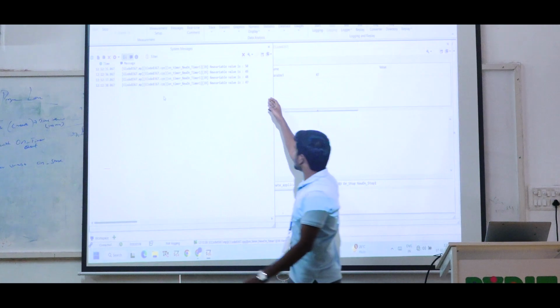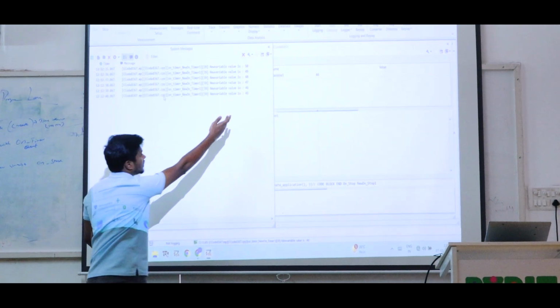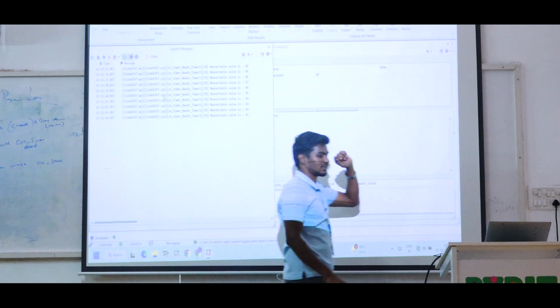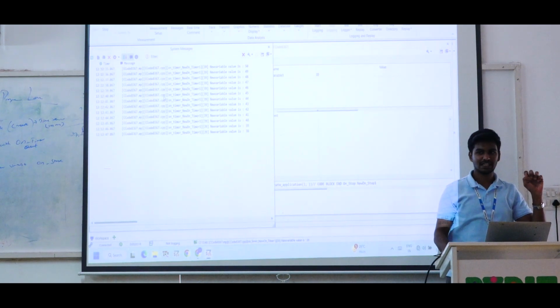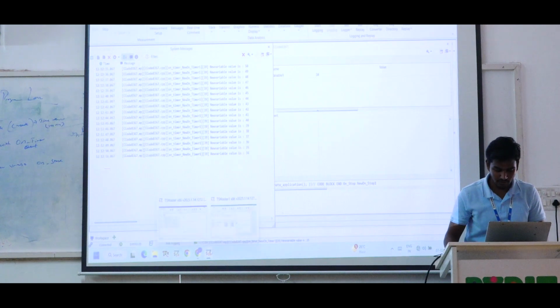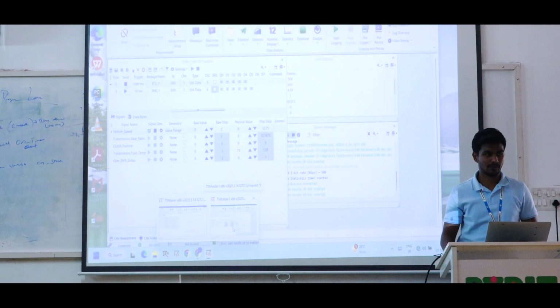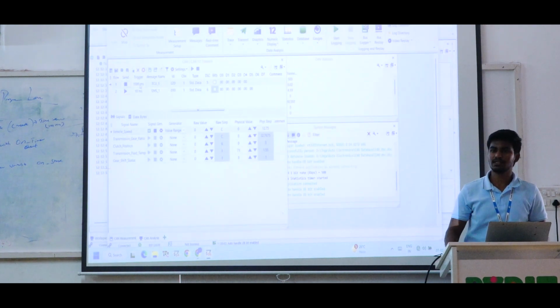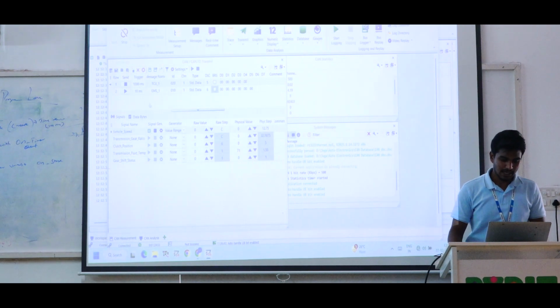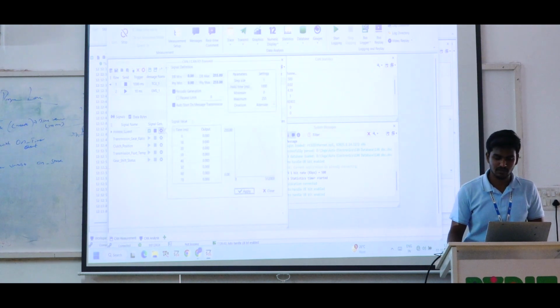So now the values will be in decreasing order, like 50, 48, 48, 47. Go to that previous tab, where we have the CAPL scripting. It is there, just a little bit confusing, so don't get confused. The one tab is for CAPL scripting. Why I am changing this: this message will be triggered every 1 second only. And I am changing the settings also.